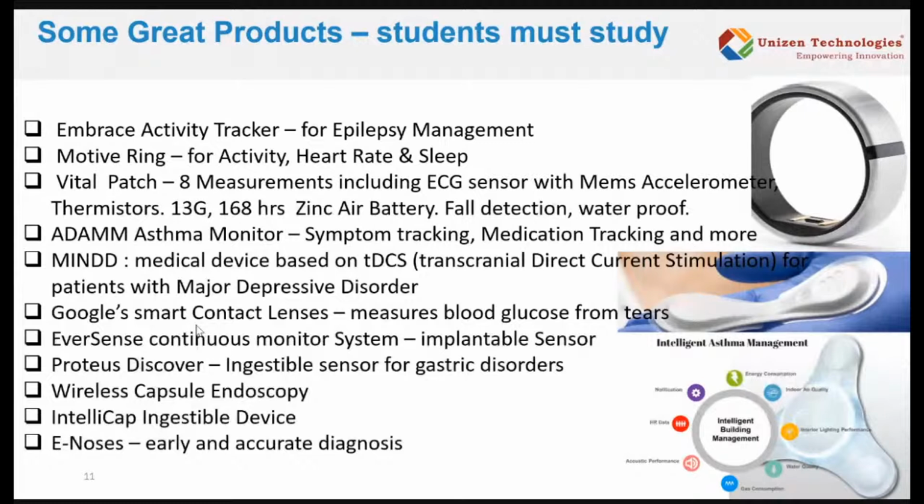In this particular design, we have used the Dialog Semiconductor DA14531 microcontroller. I'm coming to that in a little more detail. So this microcontroller does Bluetooth communication to the system, and also there is a flash. All of them are a little taller than the temperature sensor we have used, that is the TMP116 from Texas Instruments. So that means these components should be on one side of the PCB and the TMP116 should be on the other side, or mechanically speaking, that is how we have done that.